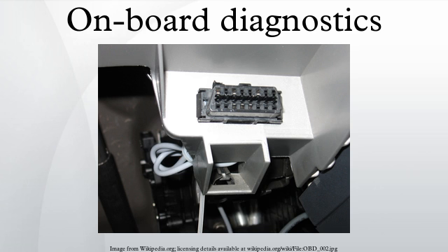This includes clearing the stored pending confirmed DTCs and freeze frame data. Mode $5 displays the oxygen sensor monitor screen and the test results gathered about the oxygen sensor. There are 10 numbers available for diagnostics: $1 rich to lean O2 sensor threshold voltage, $2 lean to rich O2